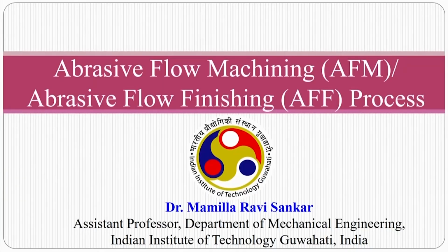For that purpose, semi-solid type tools were developed, and you just extrude across that section, so it will deburr it. Deburring is nothing but a machining operation. That is why, when this process was invented in the 1960s, it was called the abrasive flow machining process. Gradually people started using it for finishing applications. That is why this process is also called the abrasive flow finishing process.